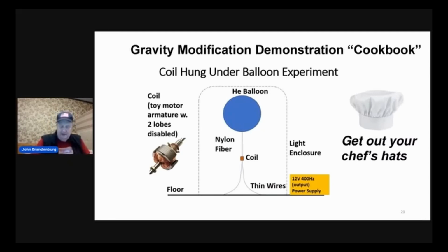If it comes on, this effect appears as voltage squared, and if you don't supply enough voltage, you won't see anything. You have to get that output voltage up above 12 volts, and you have to have frequencies at or above 400 hertz. Next.